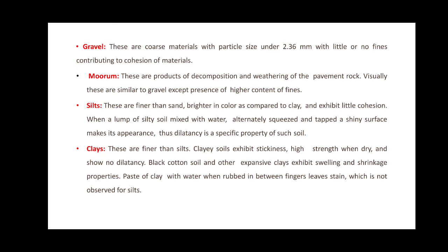Lastly are the clays. Clays are finer than the silts. The clay soil will exhibit stickiness and high strength when dry, and they will show no dilatancy. The black cotton soil and other expansive soils will exhibit swelling and shrinkage properties. And a paste of clay with water, when rubbed with the finger, will leave stains, which is not observed in the case of silts.